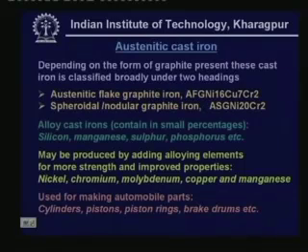All these you can see are well designated by the letters given in the name, meaning austenitic flake graphite iron. We consider one example like AFG Ni16 Cu Cr. AFG, you understand, is austenitic flake graphite.